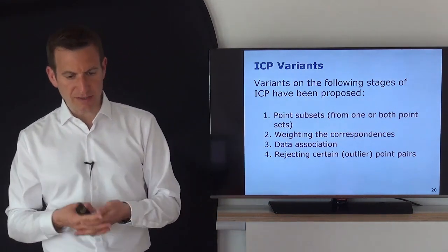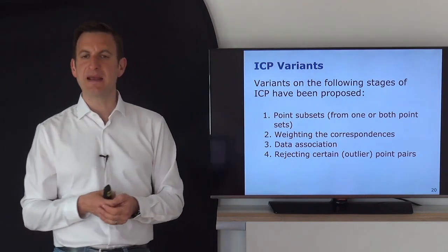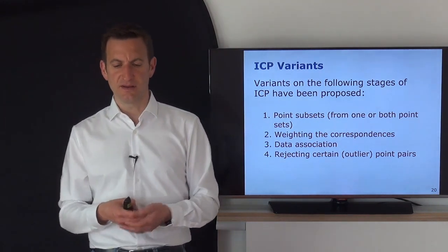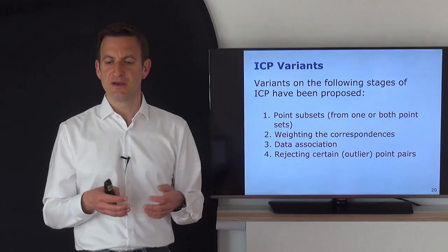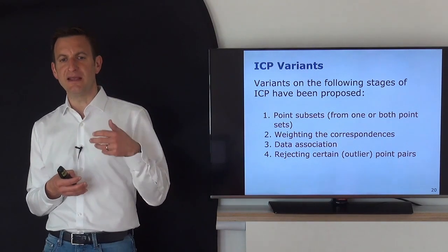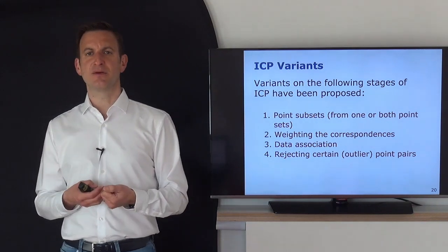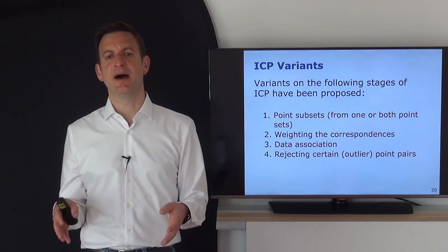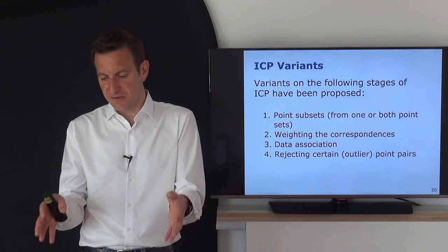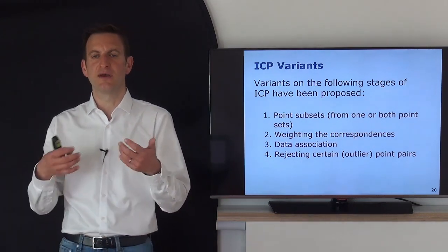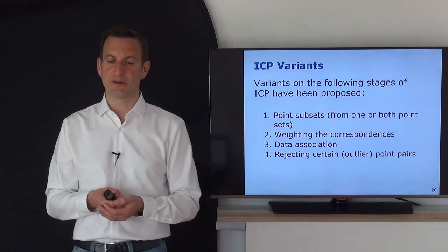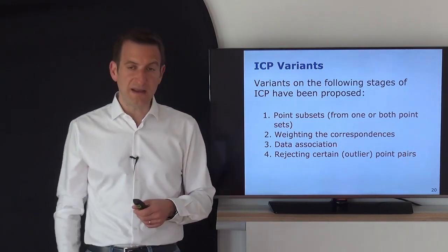And again, there are a large number of different variations that I can change. One of the things is, for example, I may not want to use all points. You may think, okay, why is this a good idea to reduce the number of points? The more measurements, the better. That's kind of the initial intuition. But there can be several reasons why I may want to reduce the number of points that I'm considering. This can be due to speed, but it can also be due to different densities of points. If I think about a typical laser range scanner scanning points in the environment, points which are nearby will give a higher density than points which are further away. And I may not want to give the surfaces in my near surroundings a higher weight just because there are more points on the surface because of the properties of the scanner. So this may be a reason, for example, to consider only a subset of points, for example, a uniform subset.